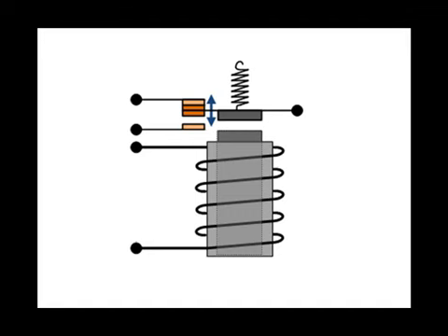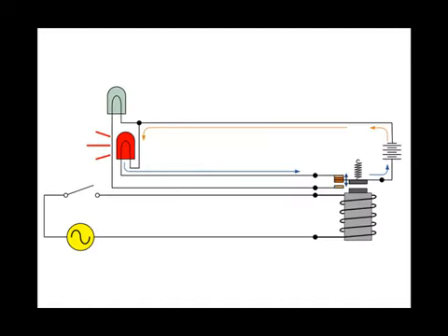Let's put this relay into an application. You could say that there are three public interfaces to this circuit. The first one, the single pole, single throw switch that is operated by the operator. The second, a red indicator that is seen by the operator. And the third one, a green indicator that is also seen by the operator. So the operator has access to control the switch, and then a red and a green LED or indicator indicate to the operator the conditions in the circuit. The power supply, the actual relay, and the DC power supply would not be visible to the operator.